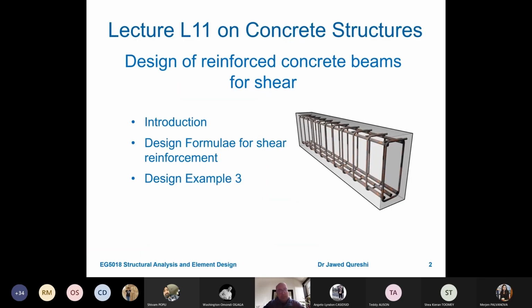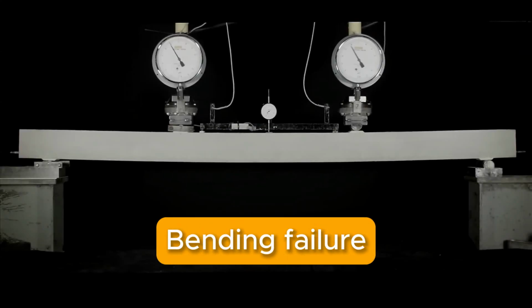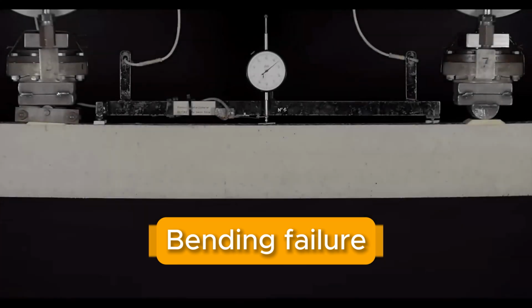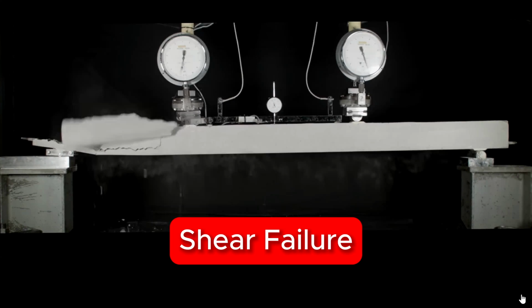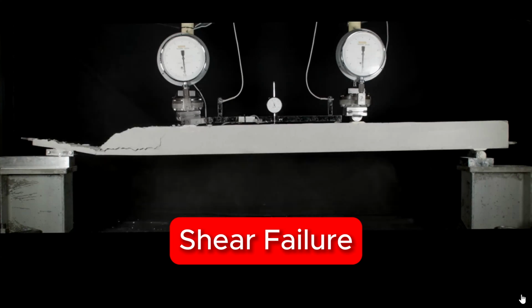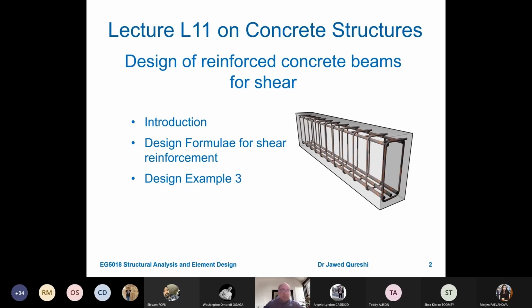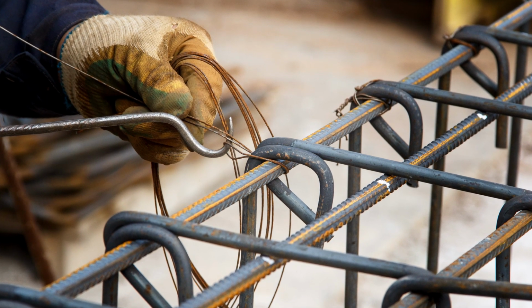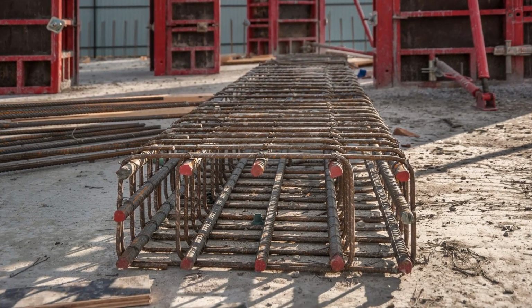Shear is a major issue in reinforced concrete beams, and we always want to ensure that the failure is in bending rather than shear. The reason is that shear failure is sudden. It is a brittle failure, and at all costs it should be avoided. The way we design for shear is to provide these rings. The rings that you see wrapped around the top and bottom longitudinal reinforcements are termed stirrups or links.